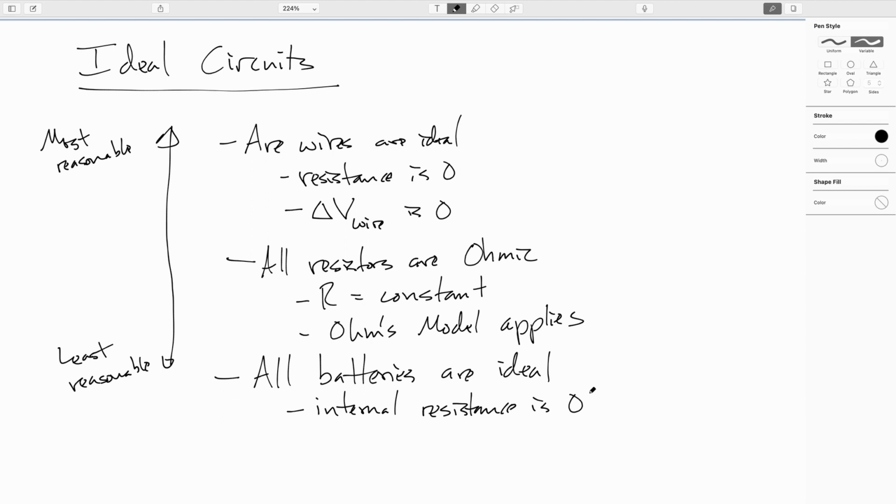Because you have ions transporting within the battery to move your charge around, those ions are colliding with other molecules in the battery chemistry. There's plenty of resistance in a battery. I mean, it's not off the charts high. It's lower than probably the devices you're hooking up, but it's certainly not at the level where you can just totally drop it down to 0.